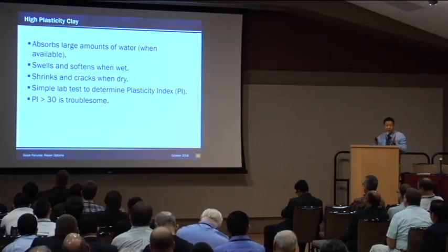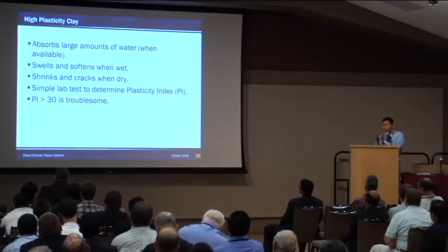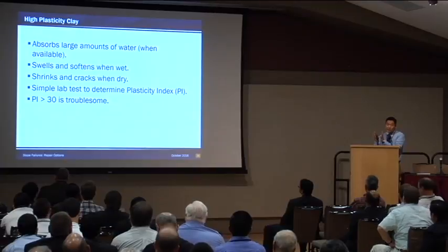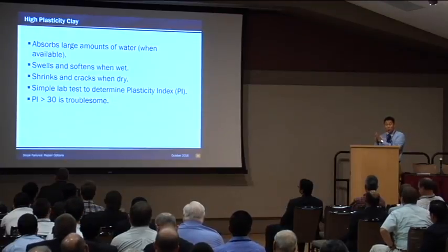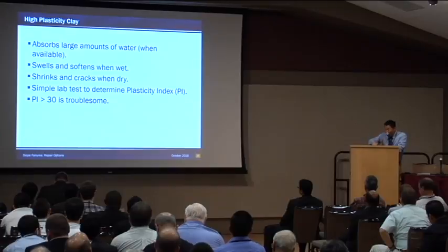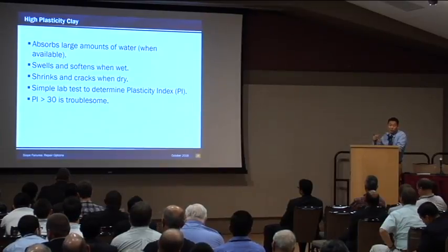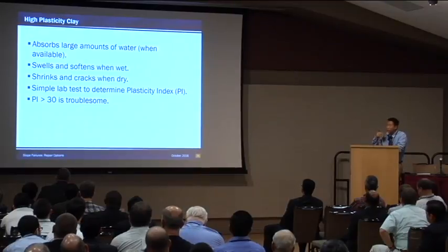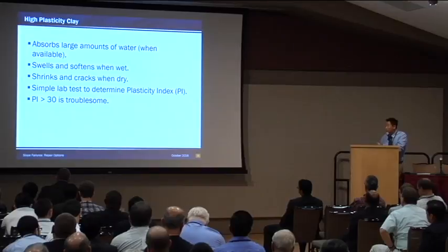The shrinkage crack in the clay opens up when it is dry, but it's not going to close down when it is wet. So that crack, the shrinkage crack, can serve as the avenue for the water to get in deeper. So basically, your embankment or slope has access to water at deeper depths.